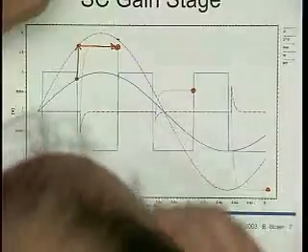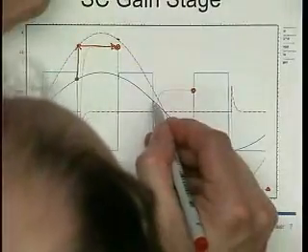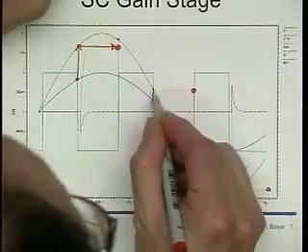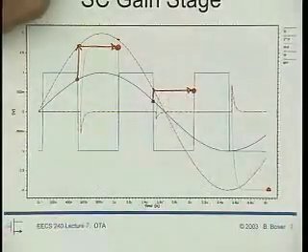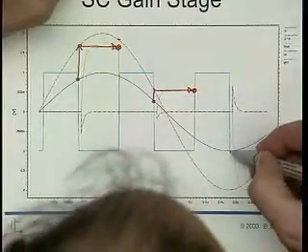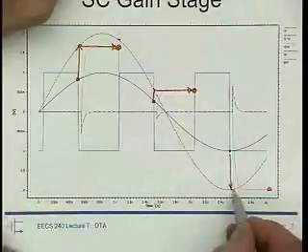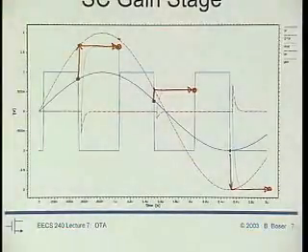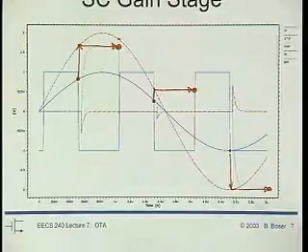You can do it again here. It grabs the value at the end of phase 1, that's this one, multiplies it by 2, and that's just the right result. One more time. Fetches the value here, multiplies by 2, and lo and behold, matches. Okay? So it's an amplifier by 2, but only at certain time instances, and it's got also some delay built into it. Well, A to D converters anyway sample, and they take their time to do the conversion, so why not the amplifier also?